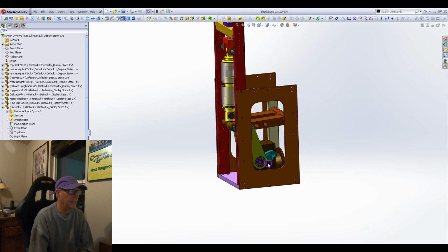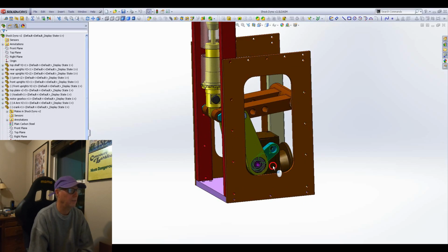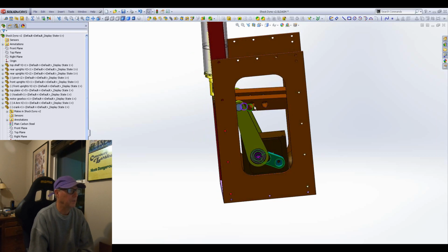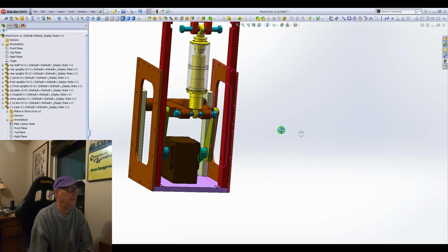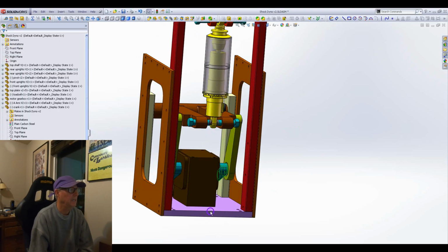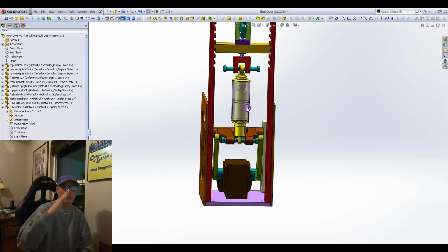It has the same setup for the crankshaft. This thing goes round and round, and it has two different crankshaft strokes, and then the A-arm has 3 holes in it. So that was carryover, but what I did get rid of is the big rod sticking through the bottom, and now the shock absorber is on the A-arm. So the shock absorber is going to push on an angle as the A-arm pivots.